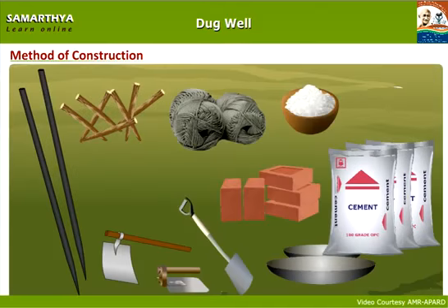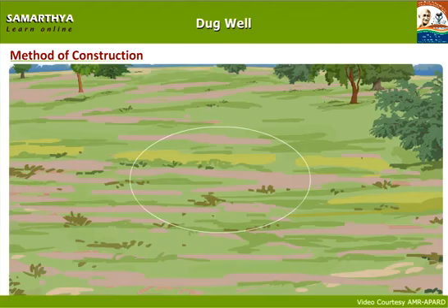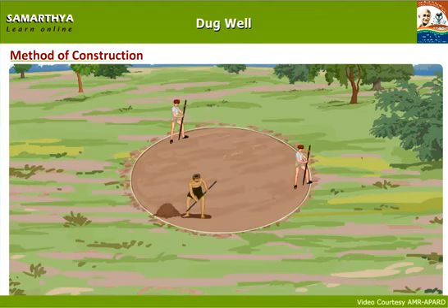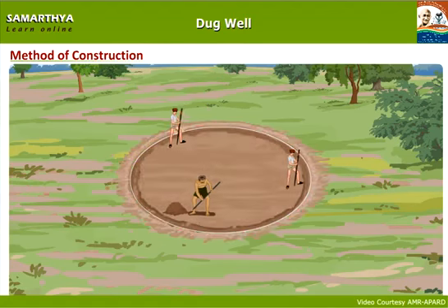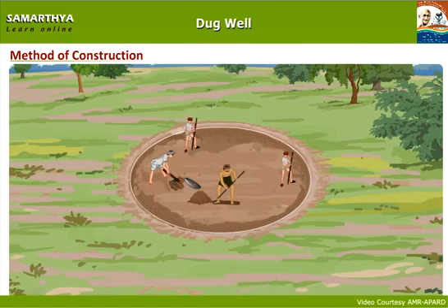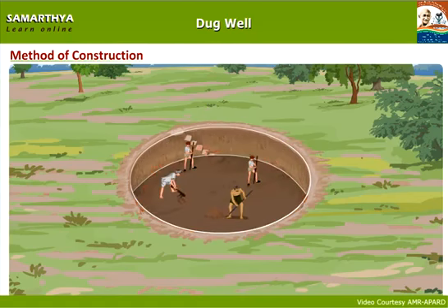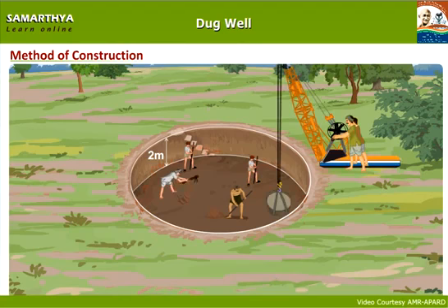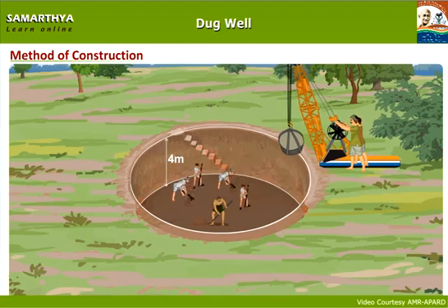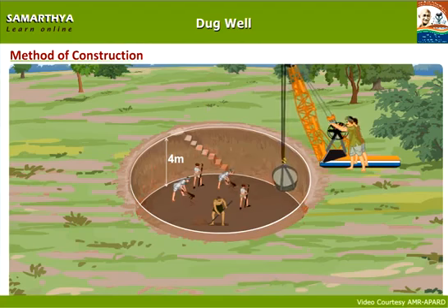Based on the implements we suggested, excavating starts at the marking place. Generally, ordinary soil is about 4 meters. Depositing the excavated soil upward from 2 meters is easy. The excavated soil after the 2 meters is deposited upward with the help of cranes.